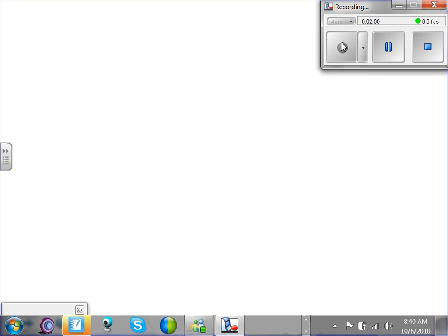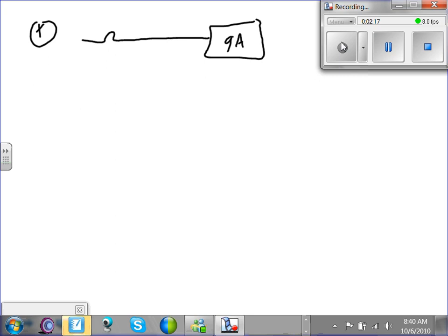All right, let's go ahead. So we know what a continuous load is. I'm going to take example number one, my friends, and I'm going to be doing a lot of drawing today. I have a 9 amp load, and for this 9 amp load I need to find, first, the overcurrent protection device, and second, the conductor. We're going to be sizing overcurrent protection devices and conductors for loads.